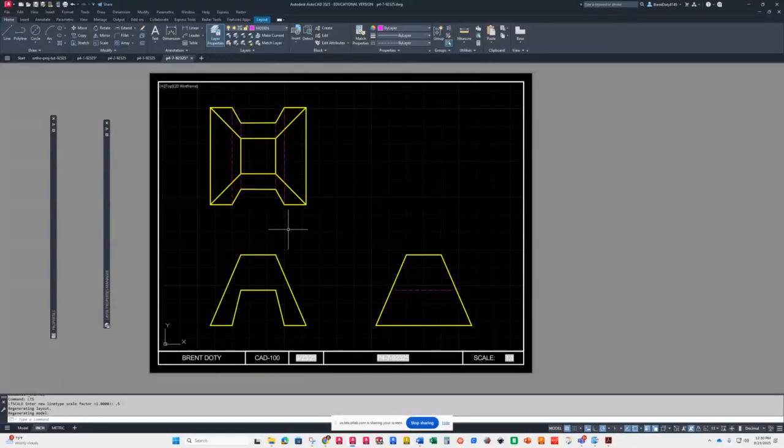So as you can tell there, mine changed, but I can still see them and they look good, so I'm pretty happy with that. So I'm going to deactivate. Remember, you double click out here in the gray, or you double click inside of your paper to activate, out here to deactivate, or you come down here with paper. It's paper and model down here to change between the two. All right. Questions on that one?